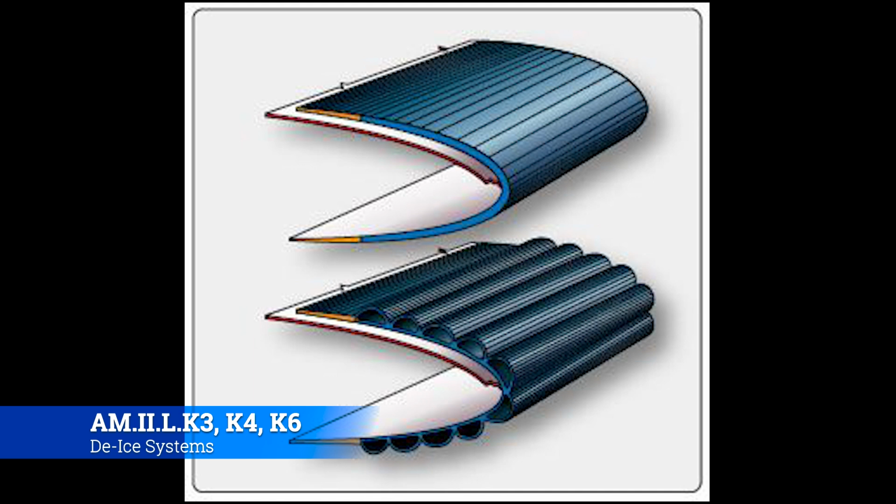Now, whenever it's not in use, the air pump that's being driven by the engine still runs, except it's set up so that it sucks air out of those boots. That causes the boots to suck up close to the wing, and you don't have to necessarily pay in terms of airspeed and performance for having the boot on there. It allows it to work just like it was a piece of sheet metal and a natural part of the wing.